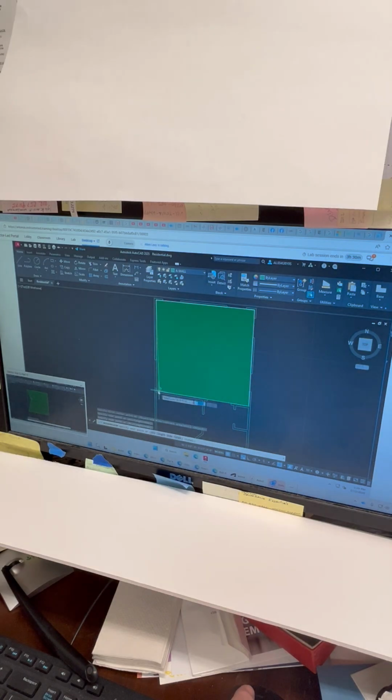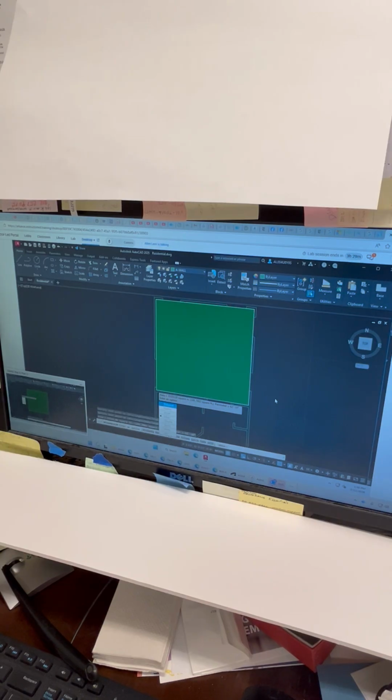All you need to do is look what the default is saying right now. It's saying total. And what I mean by that, default, is that if you hit enter on your keyboard, it's going to accept that default, total, and it's going to total up between all 4 of those points that you picked. And this is 246 square feet. It even calculated our perimeter.